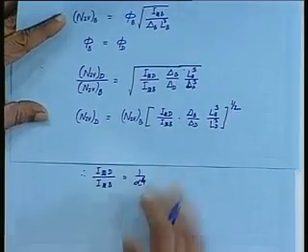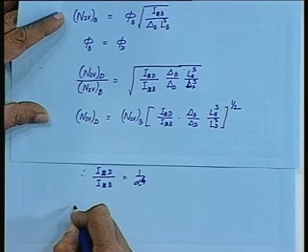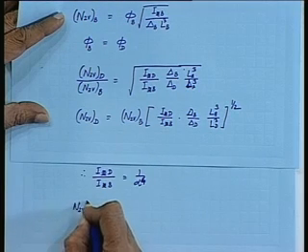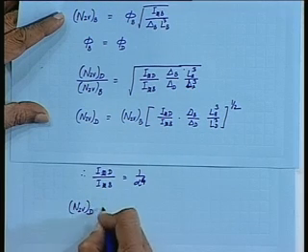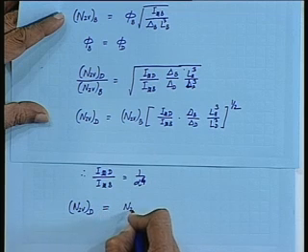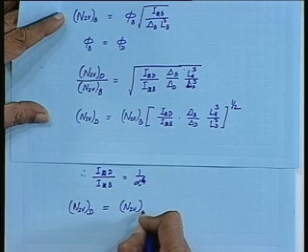After we get this for an identical type of shape, not the dimension, then plugging these values into this expression here, I will just write here for your convenience. So, N2V for the design vessel can be written in terms of the frequency of the basis ship.